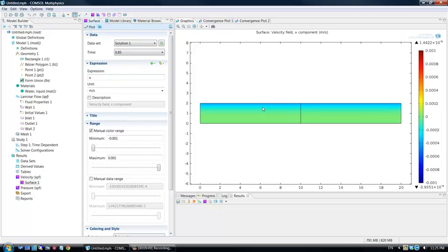And you can see here that the velocity near the plate is dragged along due to viscous stresses, while the fluid near the bottom of the channel, since it's too far away, longer than the viscous penetration length, doesn't really move down here. So you can see that pattern forming just by looking at this plot.